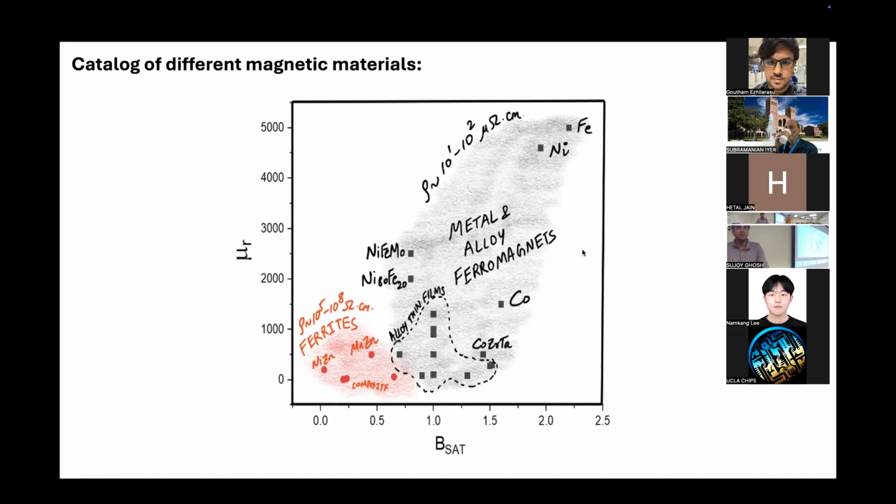Okay, so this chart, B saturation, that's in Tesla, right? Unit is Tesla. Yeah. So 2 Tesla, and it's not frequency dependent, the saturation. Saturation is, no, the saturation is frequency dependent. Yeah. So what about in this chart? Oh, you mean BSAT. BSAT and saturation magnetic field and the saturation magnetization, right? They only depend on the number of spins per unit volume. I see. Because imagine all of them are aligned, right? So what's the maximum magnetization you can get, right?